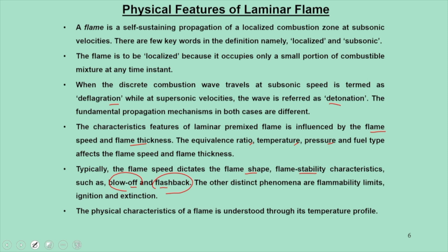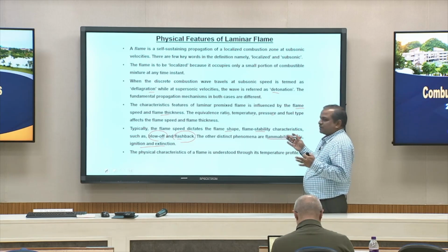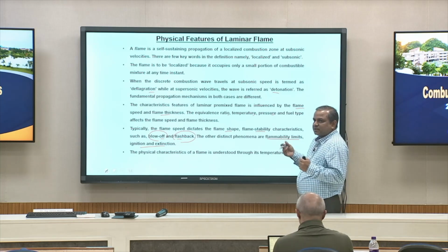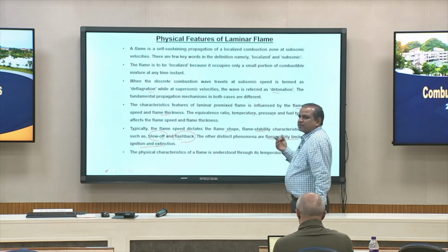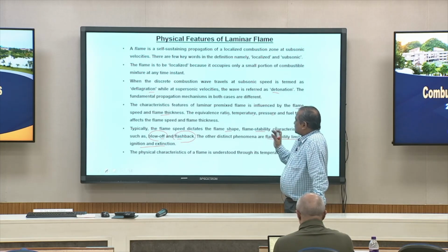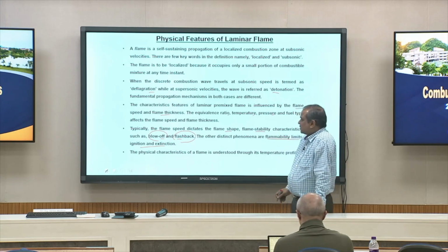The other concepts that we need to explore are the flammability limit, ignition and extinction. Normally in an IC engine, the equivalence ratio must fall in a certain range for initiation of the flame, or otherwise the flame cannot be initiated. During this period we can see a self-sustained flame, and that is why it is quantified through the flammability limit of any charge.